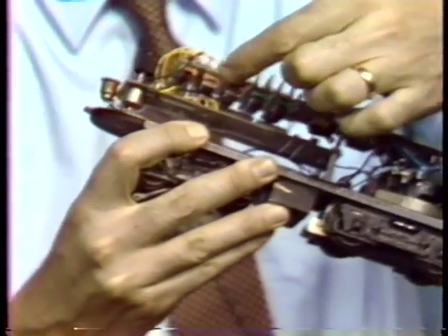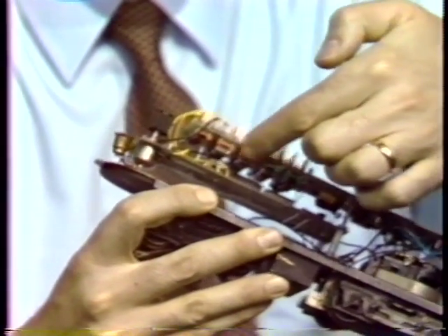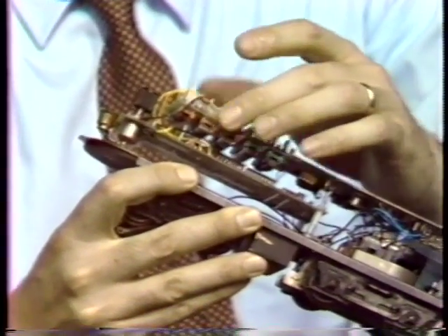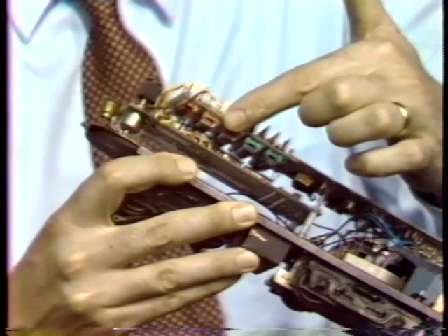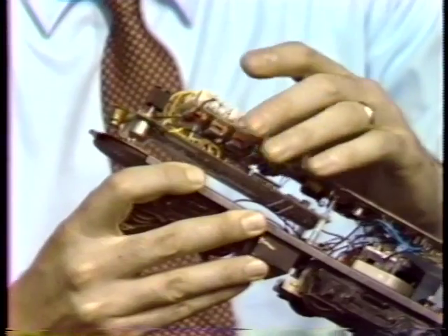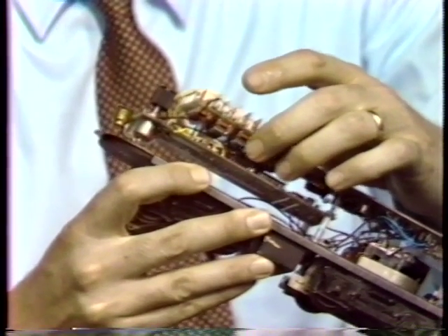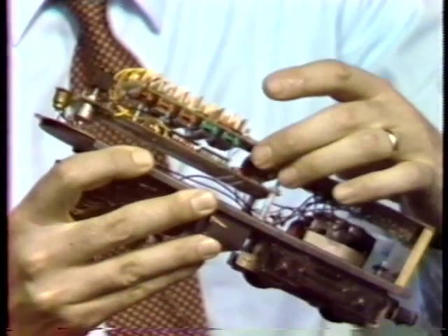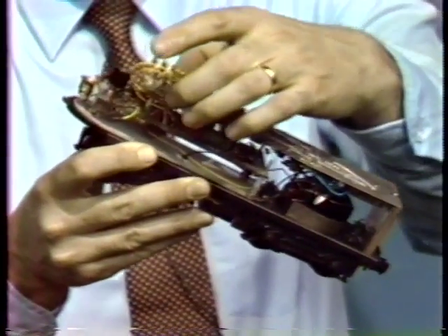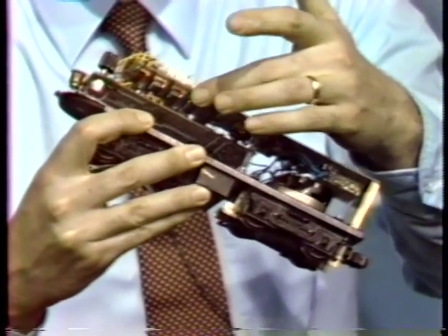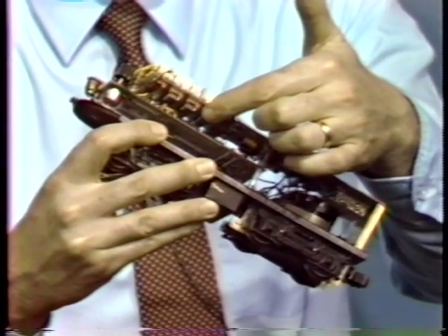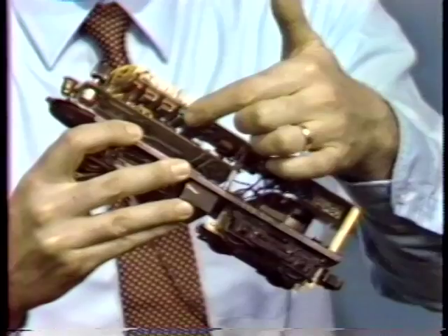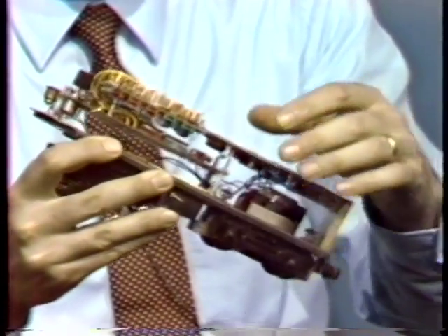All this runs off CMOS sorts of logic, which means that if I get a momentary power interruption, I can store enough power to run the CMOS for a second or two on a capacitor so I don't lose track of the state for brief power interruptions, which are fairly frequent in this kind of a system, as you might imagine. So here's the up-down counter and the D to A converter. Actually, the D to A converter is simply a resistor network running off the CMOS. CMOS makes a very nice switch, and so I use that technique to do the D to A conversion.